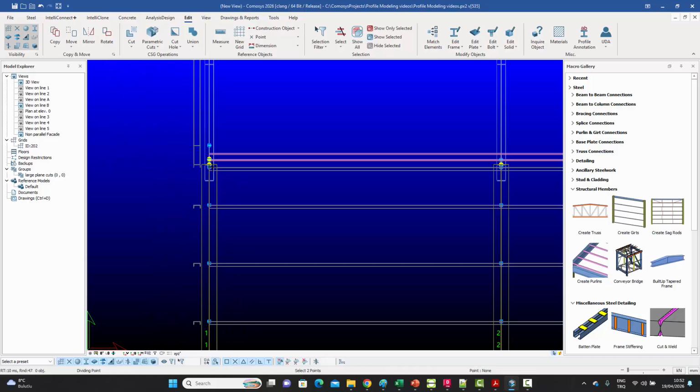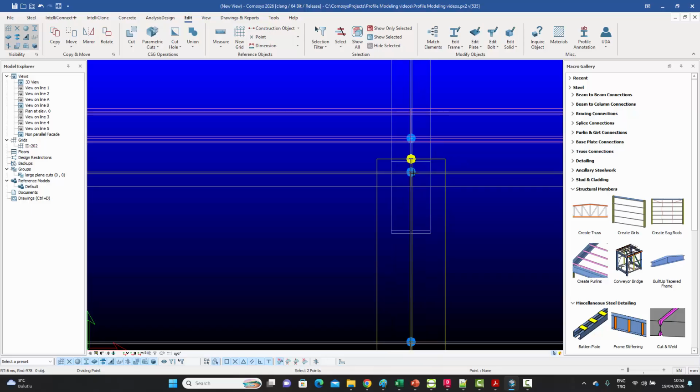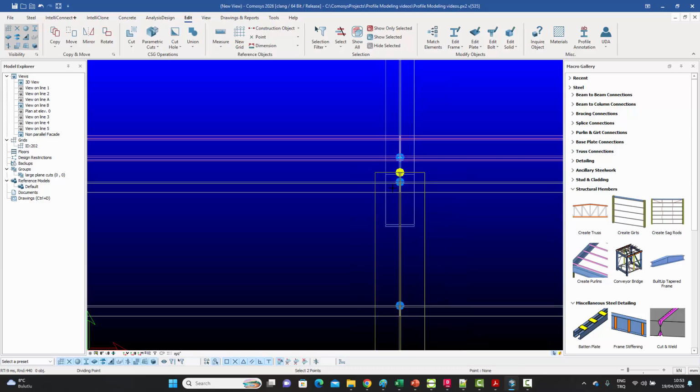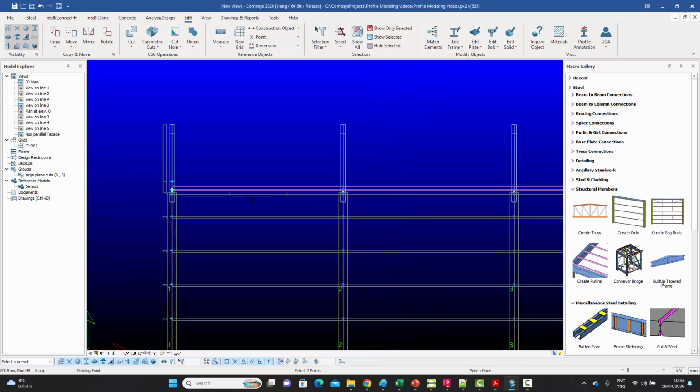I just need to make sure that I'm clicking on the right points. And before I click on this one, I keep the 2 number key pressed, so that it's divided into 2 parts like that. 2 points are created, equidistant. In fact, it's a good idea to measure the distance between them, 1667. That's correct, 1666.6, which is basically rounded off to 1667 in the drawing.